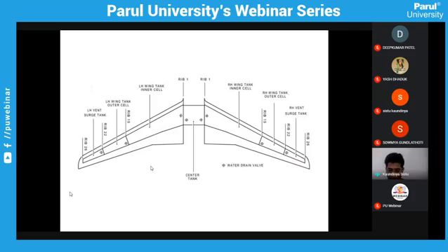Okay, technically I can agree with you, but practically no. As I said, if you have a few liters difference, what you said might have worked, because both engines can take. There is no rule saying that the left engine can take fuel only from the left wing and the right engine only from the right wing. You can pump both fuels. Both the left and right engine can take from the right tank.